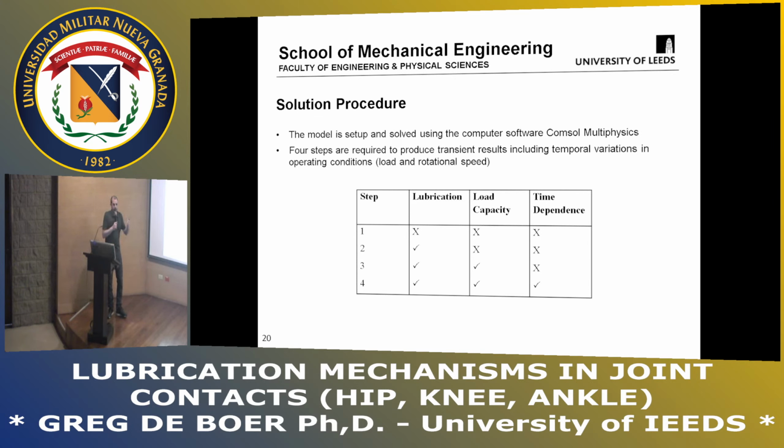So again, an idealized model. But in order to get to a problem which is fully transient, so time dependent, we have several steps that we use to build it up. So this is just explaining that it's not a case of just solving all the equations. It breaks if you try and do that. So we need to slowly evolve the solution towards one that can work. And what's important here is that when we get to number 3, we have a steady state solution, which includes the lubrication, the solid mechanics, and this load that we want it to match. And then we can use that to look at time-dependent problems.